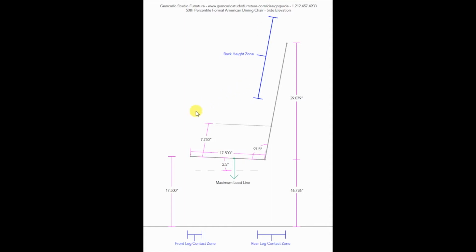The gray line that defines the seat depicts the plane at which the buttocks of the user must be supported. If the seat is cushioned, the cushion should extend above this line by the amount necessary to compensate for the compression ratio of the specified cushion. If the seat is not cushioned, the seat should meet and follow the profile of the drafted seat line.